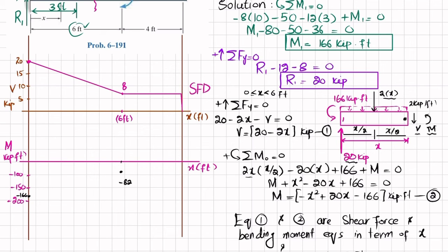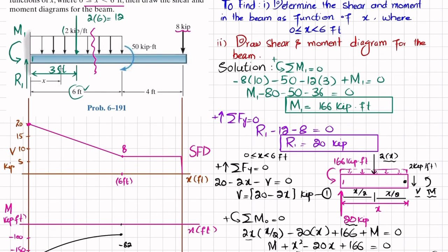Now you can see that shear force is a linear line with slope decreasing. So bending moment will be a second degree curve and the rotation will be in clockwise direction. So we'll join these 2 points by using a curve. At this point, you can see you have an external moment of 50 kips into feet, that is clockwise.